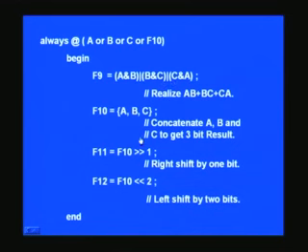These instructions will be so to say executed only when any of these inputs change from the previous value, right. And if you have multiple statements like this, you need to put a begin and end indicating the whole thing is blocked as such. In one block you can put as many instructions as you want really. And another thing is when a statement is complete, you just end up with a semicolon there.